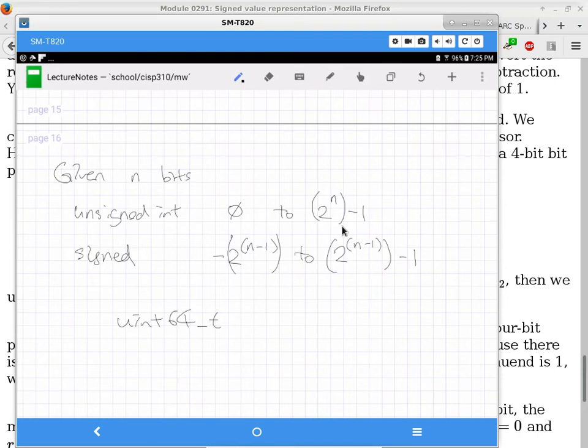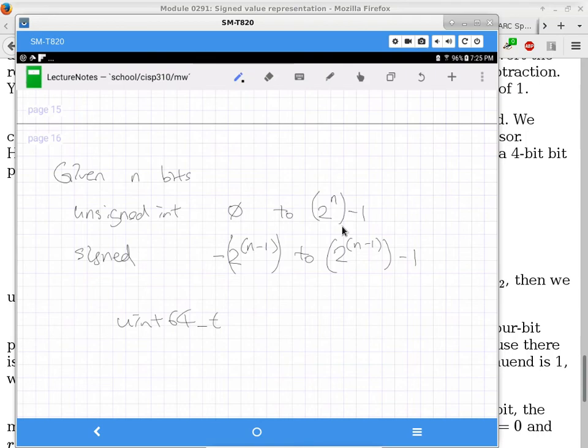So this is going back to what I said a little bit earlier. If I look at the student's program on a PC and say, you really should be figuring out what the default size of your integer is, and then declare and use these notations, uint and then the width of the integer, the student is going to come back and say, but it works. Well, I'm not going to argue with that. I can see your program is working on the PC. But if it is not changed like this, and it is recompiled to a smaller architecture, then the program doesn't work anymore. Now, in hindsight, it's always 20/20.